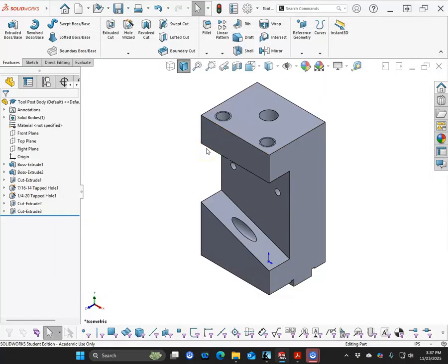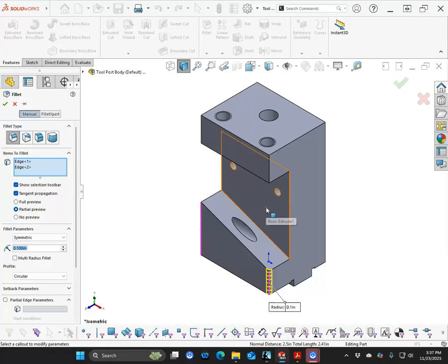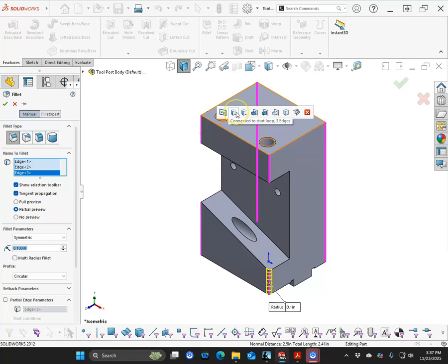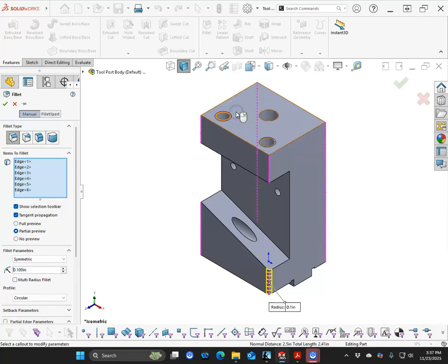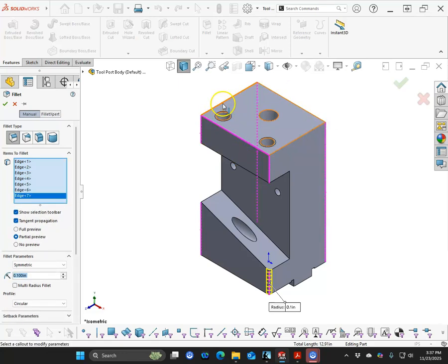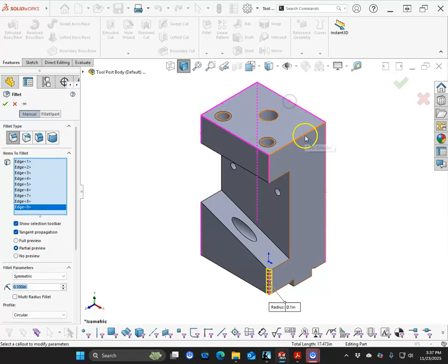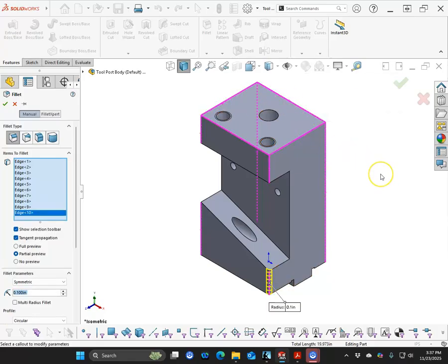Okay, so the radius is 0.063, basically all the way around. I don't see that I've made any really crazy misses, so let's go ahead and start picking some fillets. I can go through and select on a couple and then see if it will pick the rest for me. And we're kind of fighting that internal external.